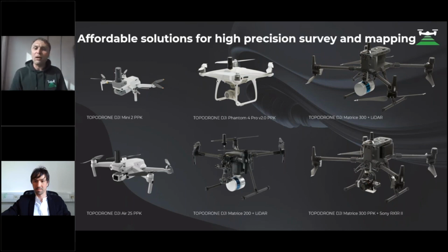And after that, I decided to combine this global shutter camera together with a GNSS receiver, and wondered what results I would have. And finally, as soon as we made the first integration and the first results, we received accuracy between 10 and 20 centimeters without using ground control points. And 3 years ago or 5 years ago, it was incredible. It was an outstanding solution. Why? Because all survey drones cost more than $10,000. And Phantom 4 Pro with an additional installed GNSS receiver provides very good accuracy, which is enough for surveying, and the price of such a solution was very, very low, less than $4,000.